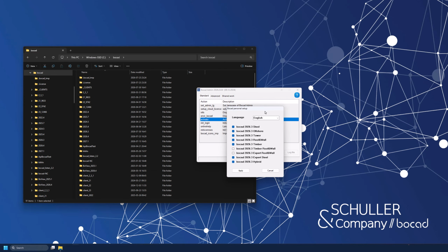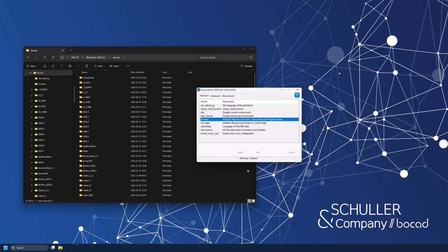And the final step would be that we are going to work in a US environment. So here I just want Bocad Tower to be activated. So US English Tower, apply. Of course, to have access to this US Imperial option, you need to install the software with both metric and US Imperial settings, or configuration, I could say. If that is missing, you would have to launch the installer again and activate that environment as well.